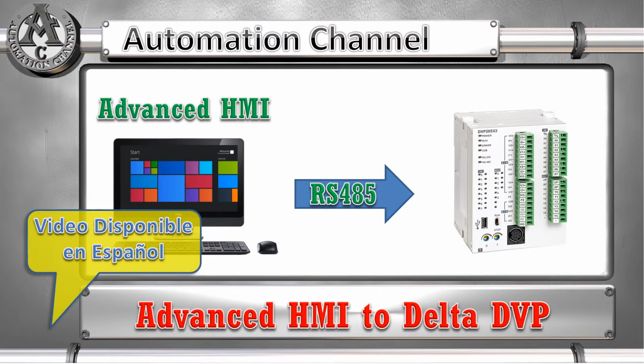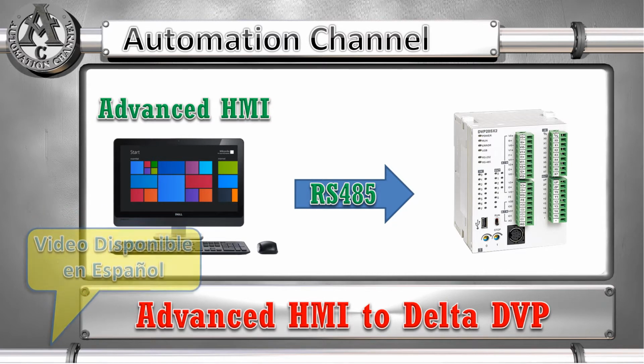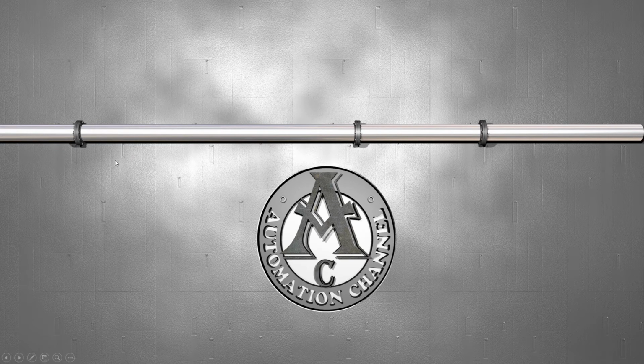In the following video, we're going to establish a connection between our PC and our Delta DVP PLC. We're going to be using port RS485. The protocol is going to be Modbus RTU, and on our PC, we're going to be using Visual Studio and Advanced HMI to establish the communication.